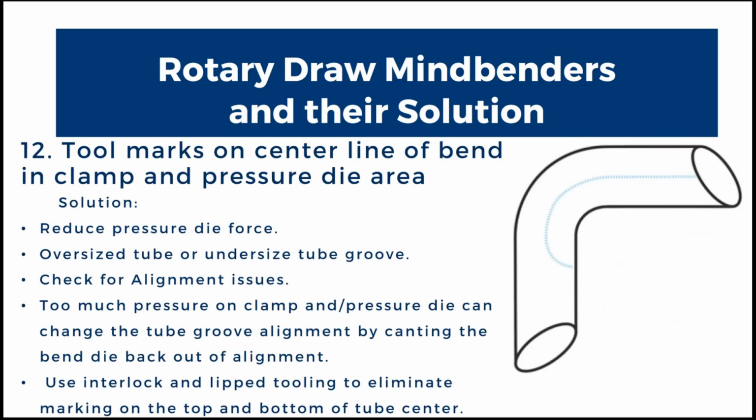Issue number 12. Tool marks on the center line of bend in clamp and pressure die area. Solutions. Reduce pressure die force. You could have oversized tube or undersized tube groove. Check for both. Check for alignment issues.